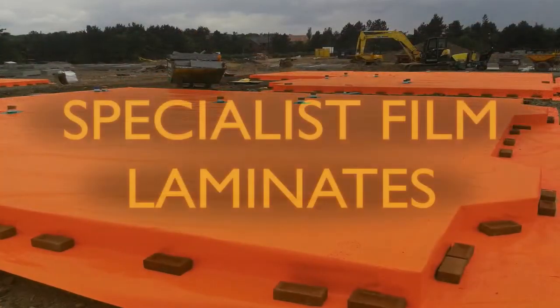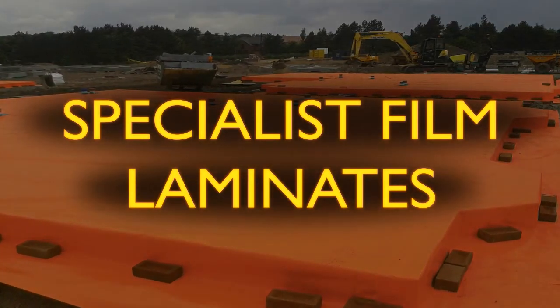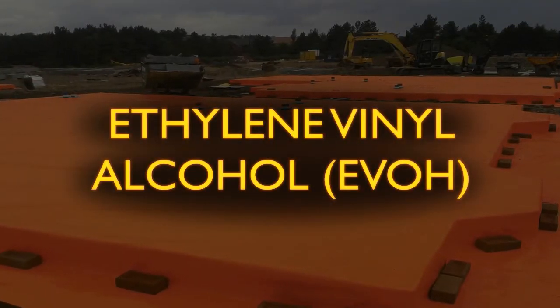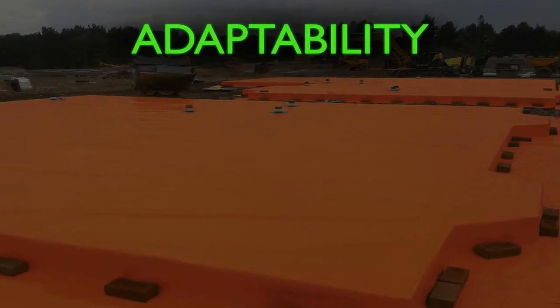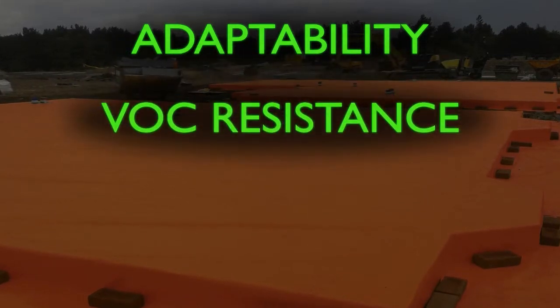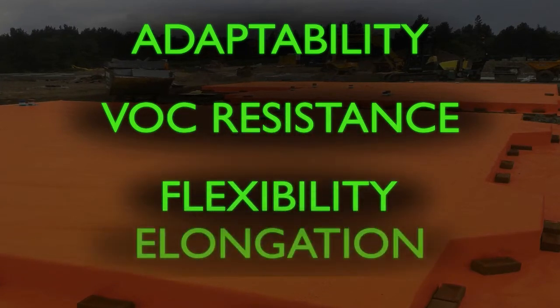Specialist film laminate membranes. These type of membranes are similar to the foil core membranes as above, but replace the foil with a specialised plastic film such as an EVOH. This allows the performance of the membrane to be adapted to meet application-specific barrier requirements. EVOH membranes offer good resistance to a variety of VOC contaminants while still allowing the membrane to retain good physical performance characteristics such as flexibility and elongation.